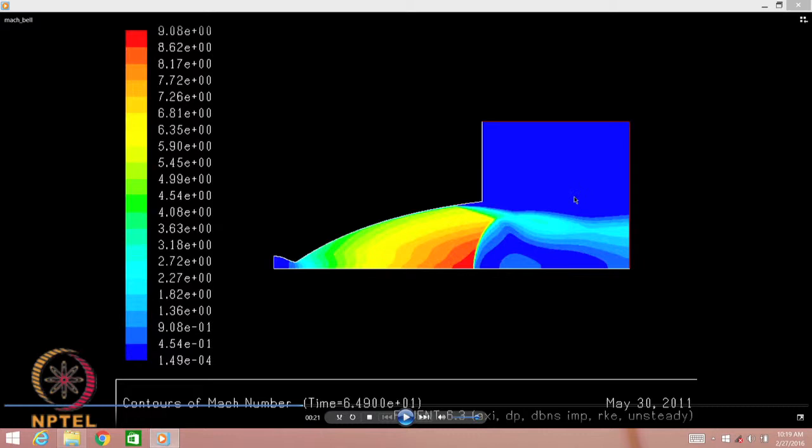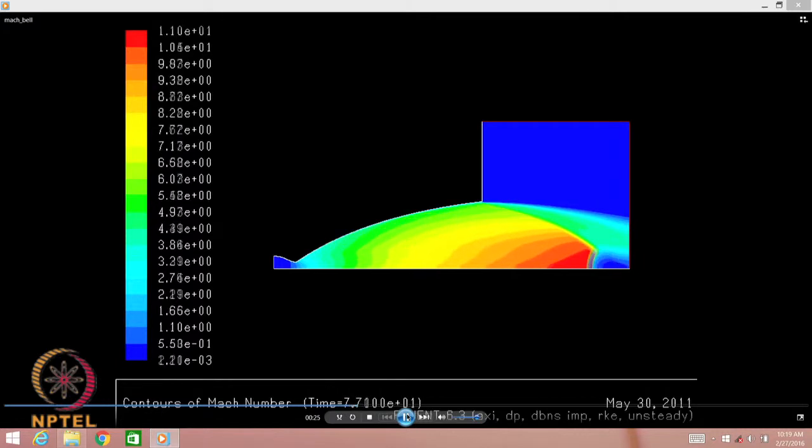So, in this case, the value of PB which creates this kind of shock, sitting just at the exit, is your P critical 2, and any critical pressure lower than this but more than P critical 3 is called overexpansion. So, now you see an overexpanded jet outside the nozzle. If I play it further, from here on it is all overexpanded.